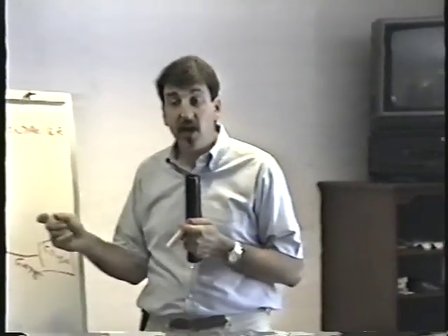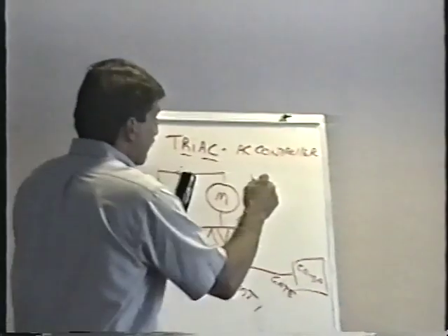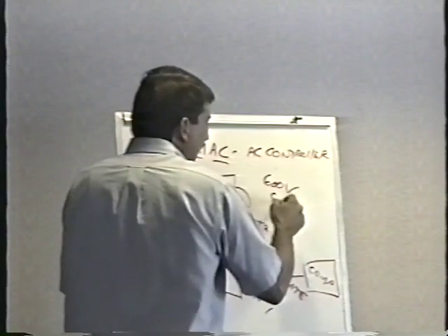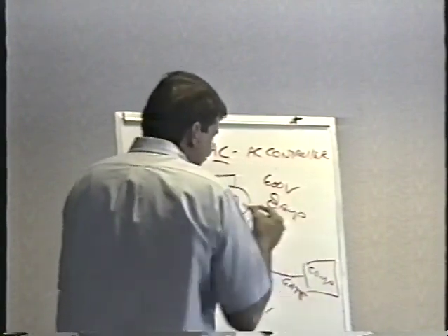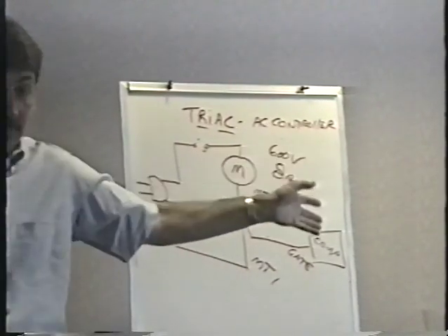In fact, you can even get these things at Radio Shack. I don't even stock triacs because they do have at Radio Shack like a 600 volt, 8 amp triac. And they're rated by voltage and current the same exact way that diodes are.